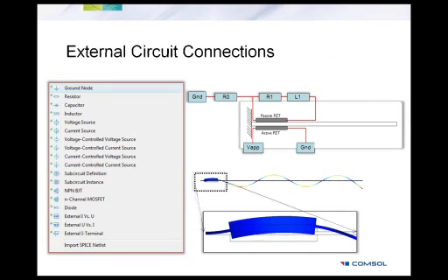And this is actually a particularly useful feature in other cases as well. Let's say you want to develop a piezo transformer, and to measure the gain, you would need some kind of a resistive load. To add a resistor to your model, you can use one of these components, which is shown on the left side. You can add resistors as a load, and you can calculate the gain of a piezoelectric transformer, for instance.